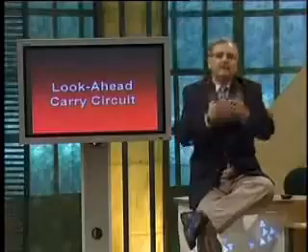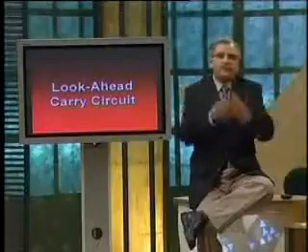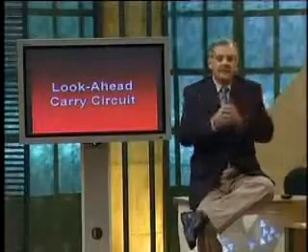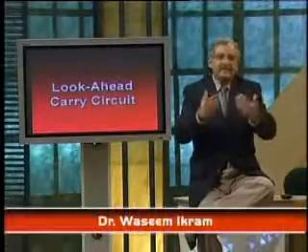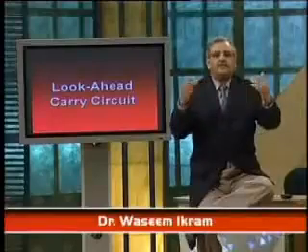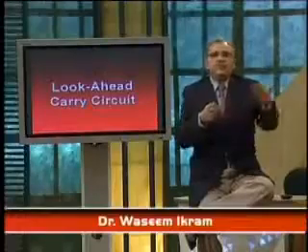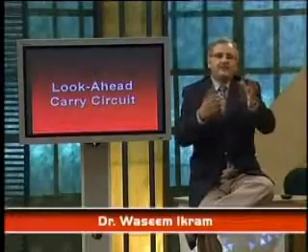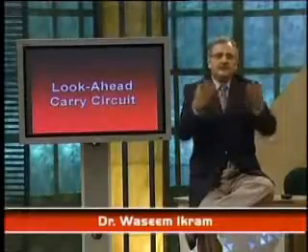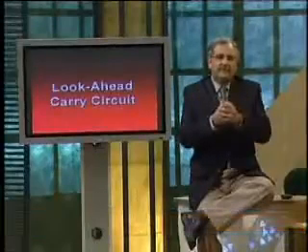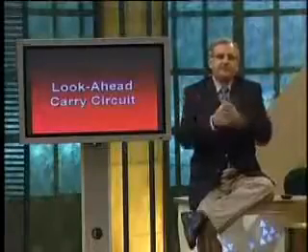The parallel adder was formed, then we said the carry has to propagate through the 4 parallel full adders. That is going to delay the carry. So what is the solution to that? Basically, we said we need to generate a carry based on the inputs applied at the full adder circuit. So we have a look ahead carry generator circuit, which generates carries which are delayed by a factor of 2. Finally, we looked at the MSI chips commercially available. Again, as we have just looked at an example, we can connect different chips together to form a 12-bit adder.